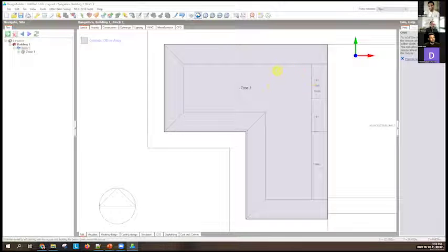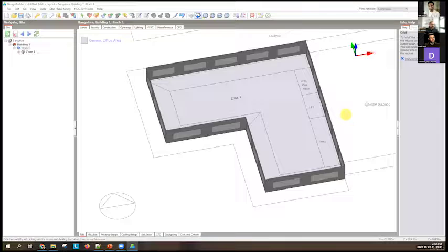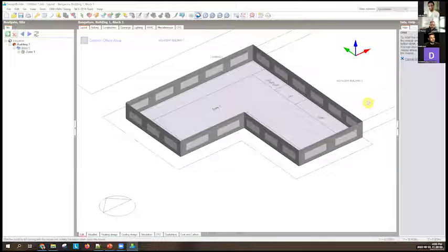It's like a fairly large open floor plate office, but you've got these unconditioned zones: plant room, lift shafts, toilets, and I'm not going to be conditioning that. So what I'll do is I'll separate this out into a zone. And the way Design Builder works, you can have a physical wall which separates things into zones, and that's over here.